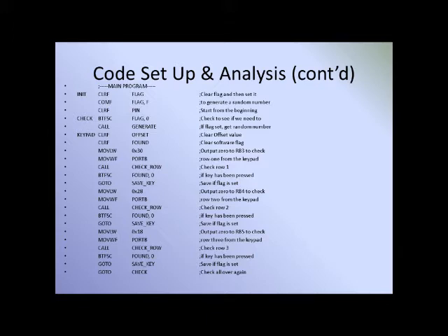For this reason, a second software flag called found was utilized. In addition to that, an offset was determined during the keypad check that would allow the program to know the numerical value of the key that was pressed. Both of these registers were cleared at the start of the keypad portion of the main loop. In order to check whether a key is pressed or not, a 0 has to be applied to each row. This is of course done one at a time.